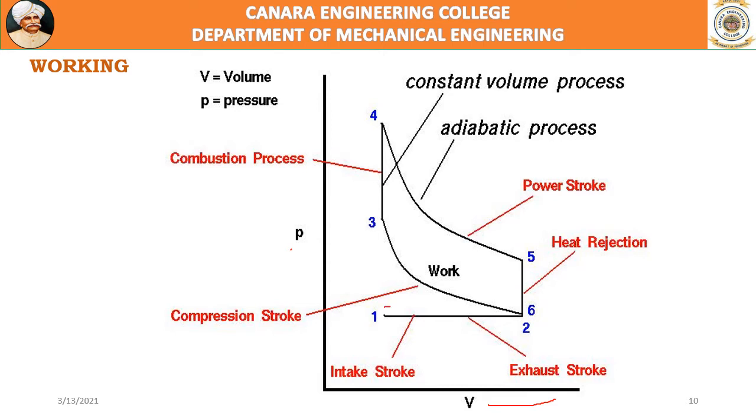Observe the process from 1 to 2, wherein volume increases from V1 to V2. It is the suction stroke. Suction of the air fuel mixture takes place into the cylinder. Then 2 to 3 is the compression stroke, where the air fuel mixture is compressed from 2 to 3. The volume, you see, is compressed.